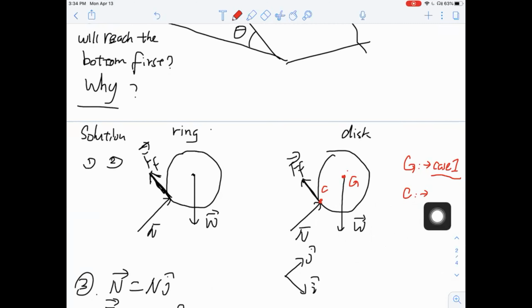If you look at case 3, you should have a point Q on the rigid body whose acceleration is parallel to the position vector r_G/Q. And as we mentioned, that's a similar case to the no slip condition. So if you pick point C, you are actually using case 3. If that makes sense.